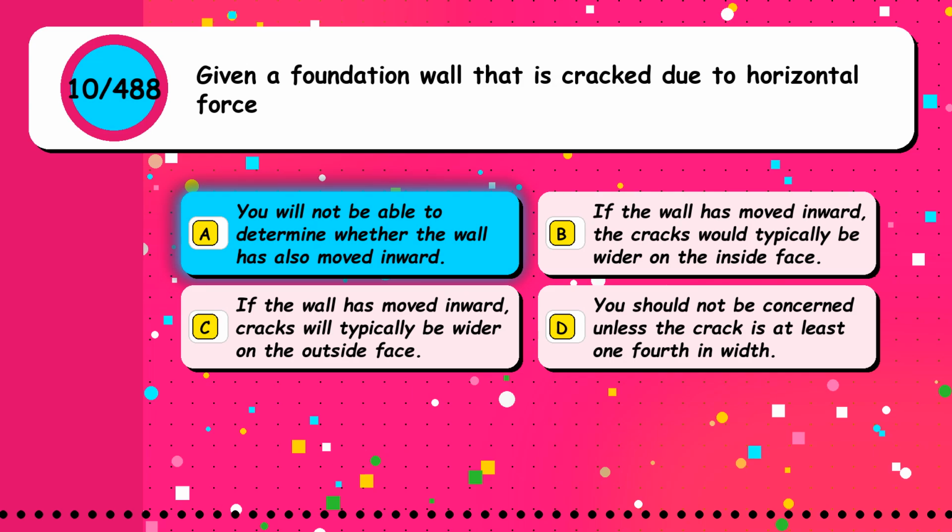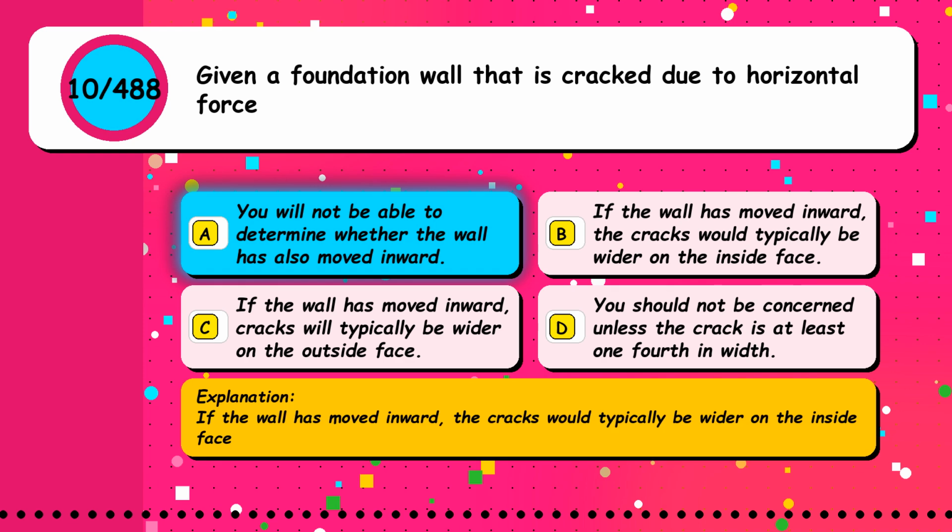The correct answer is option A. You will not be able to determine whether the wall has also moved inward. If the wall has moved inward, the cracks would typically be wider on the inside face.